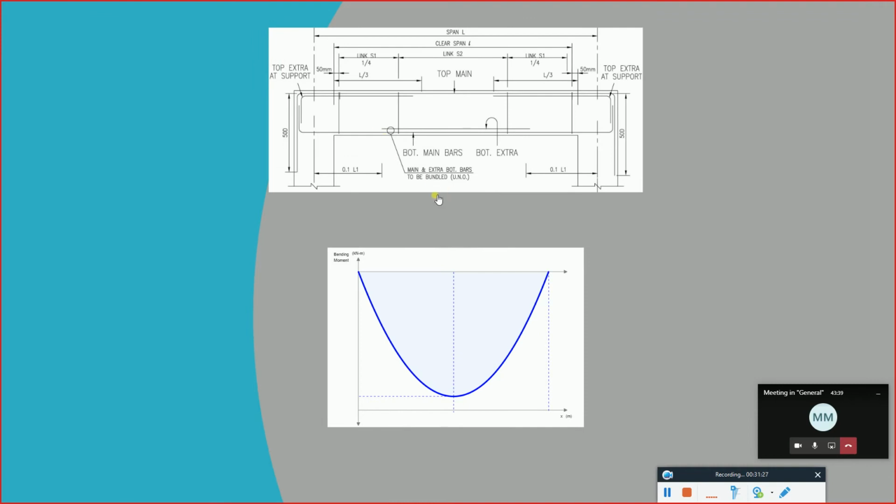We are not doing it a lot in the slab, because the bending moment for the beam will vary a lot compared to a slab, since the loading is more. So for the bottom, we divided the region into 0.1 L, 0.1 L, and then the remaining 0.8 L. We supply one reinforcement from the center of the support till the center of the support. If that reinforcement is sufficient, then that's fine.